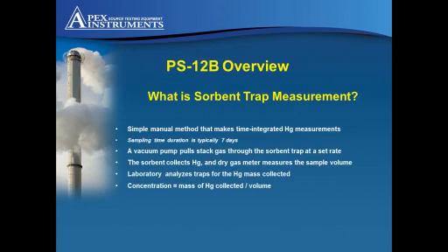Sorbent trap monitoring systems, an alternative to continuous analyzers, a method to capture a sample of the stack gas, separating the mercury for later analysis, for the standard developed by the EPA, offering a much lower cost option for mercury measurement.